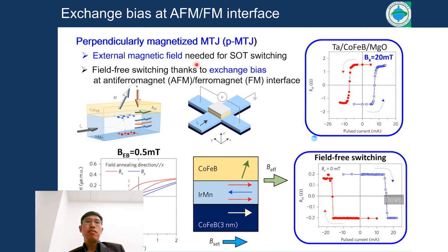But for in-plane, we don't need the magnetic field for the SOT mechanism, but as mentioned before, Professor Ono proposed interfacial perpendicular magnetic anisotropy to enlarge the density. So in-plane MTJ cannot realize higher density. So this is a key issue of this proposal from Toshiba. So how to realize perpendicular MTJ with the SOT plus VCMA?